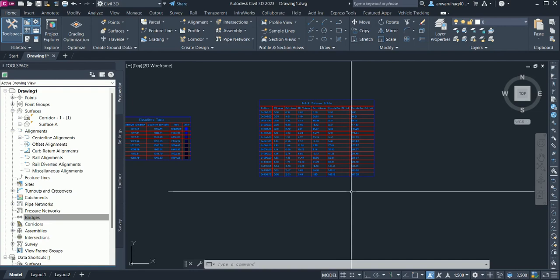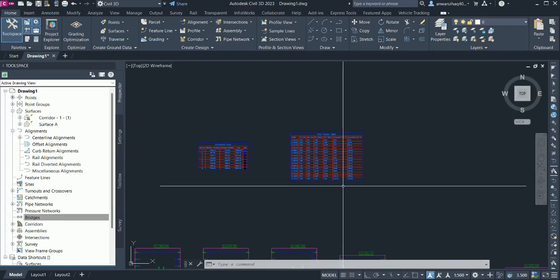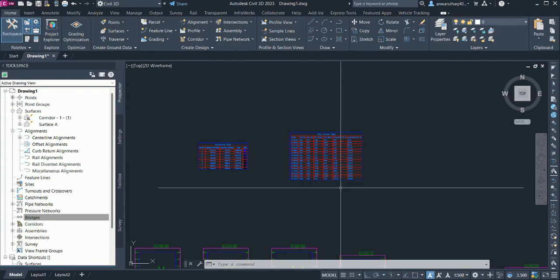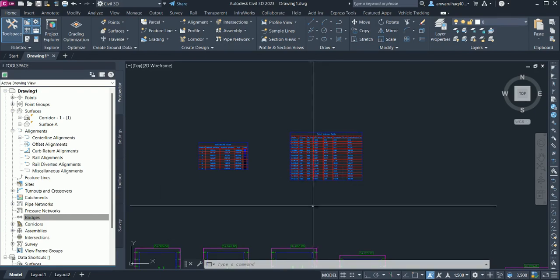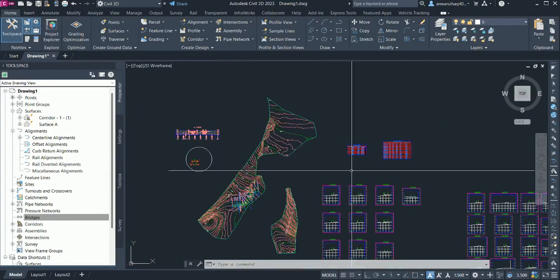If you are excavating loose material, the expansion factor is very low. So you can consider your excavation factor, because you need the dumper, and the capacity of the dumper matters. If you excavate hard rock, the bulk is more, so more excavators and loaders are required to dump the material. So like this.